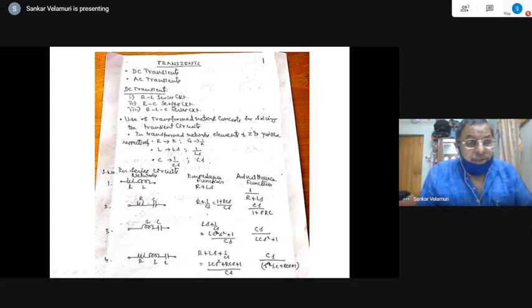Now there are series circuits and parallel circuits and any other combination that can be made. And this is DC transients. There are two types of solutions. One is the time domain solution using classical equation, differential equation solution. The other one is the Laplace transform approach. So we assume that you are familiar with Laplace transforms. Even I used to teach, before the mathematics people teach the Laplace transform solutions, reviewing them, because we have to use them subsequently.